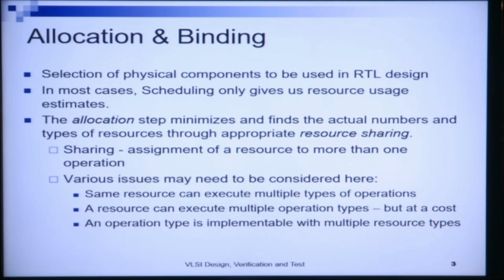Now, when we do resource sharing, we need to keep various issues in mind. For example, let us consider the case of functional units. The same functional unit can execute multiple types of operations, say. In the scheduling step, we saw that the comparison operation, the plus operation and the minus operation were all being performed using the ALU.